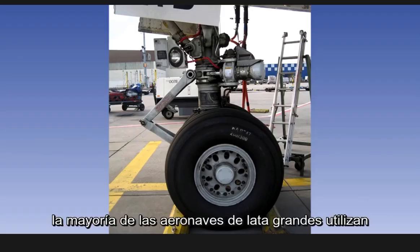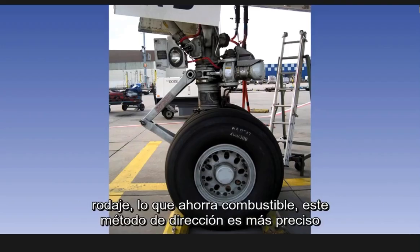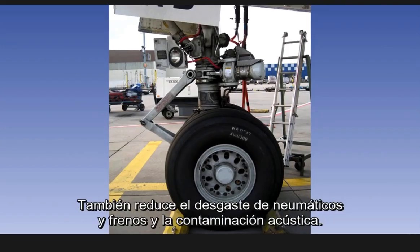Most large commercial aircraft use hydraulically powered steering systems, allowing their engines to be set at the minimum thrust for taxiing, thereby saving fuel. This method of steering is more accurate. It also reduces tire and brake wear and noise pollution.